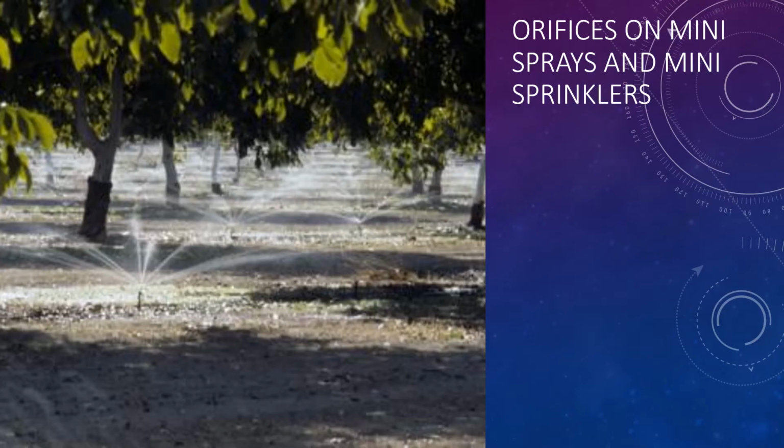In addition to the effects that silt has on filters, you saw just in the previous slide the effect of surface sealing on a media filter. Those same things happen to disc filters as well as screen filters, and a little later on we'll see an example where they had an eddy mesh screen that was basically being overwhelmed every day by silt.